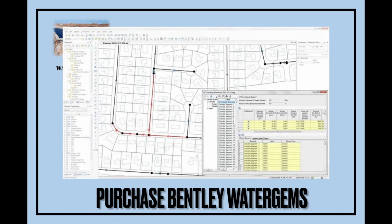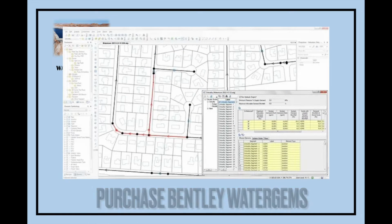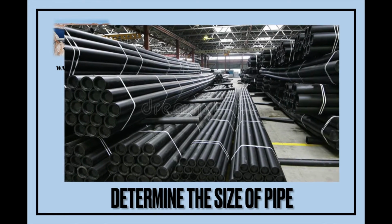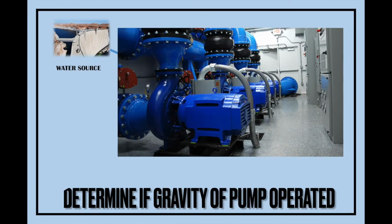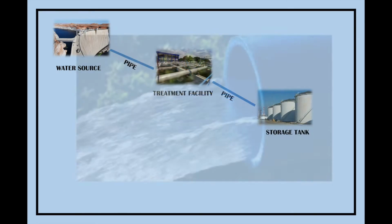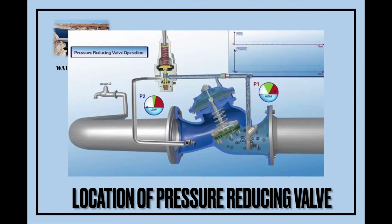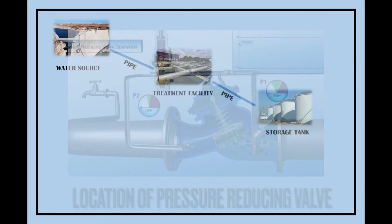Again, the hydraulic analysis is used to determine the size and type of pipe you are going to use in the project, to determine whether you need a pump or just a gravity operation, to determine the carrying capacity of a system, the possible location of pressure-reducing valves and other appurtenances.